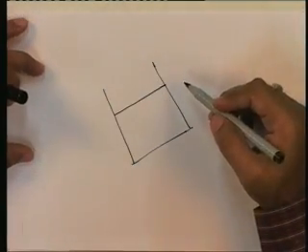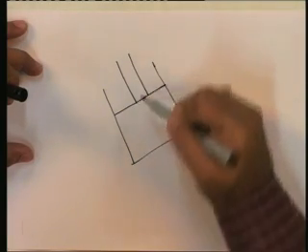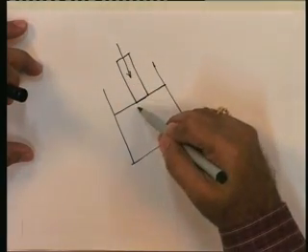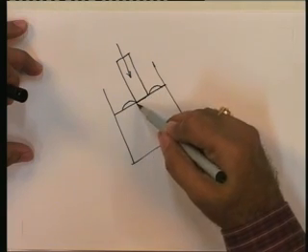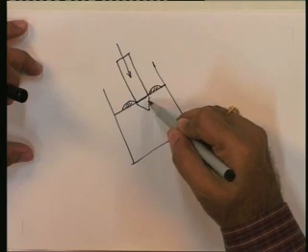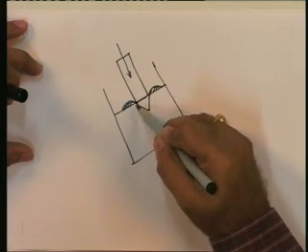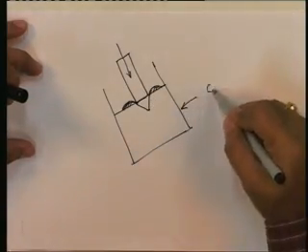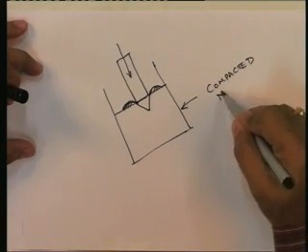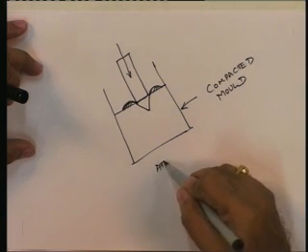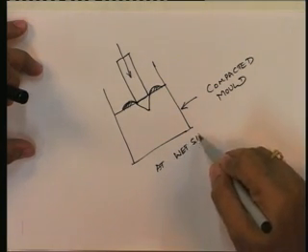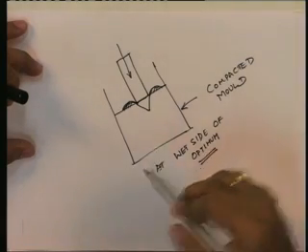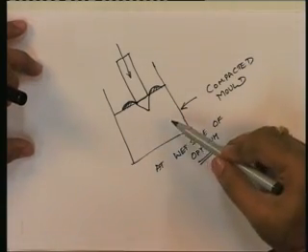At the wet side of the optimum, if the hammer energy is supplied, then the soil undergoes a typical failure, also called a heaving failure, surrounding the area where the energy is supplied to the compacted soil in the mold. The soil appears to have water oozing out of it, which is also called the bleeding of the soil.